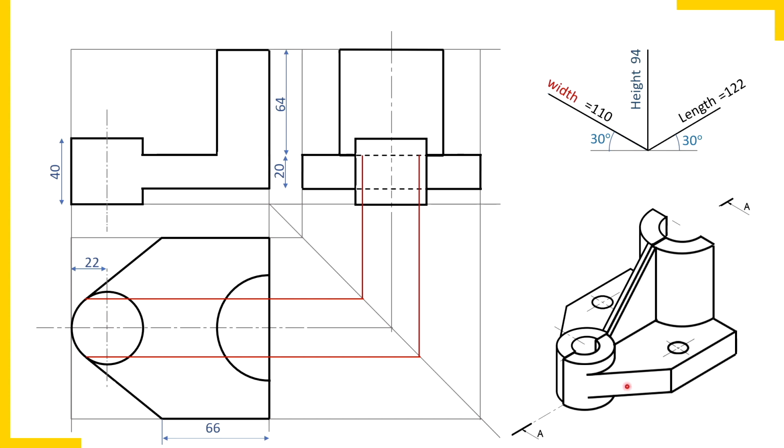So now these edges, in the pictorial view, one on the back side, one on the front side, these 2 edges here will show. So these 2 lines from these corners, we should extend up to the projector. So check here, extend it here, extend it here. Similarly on this side, focus here. I have extended up to the projector.